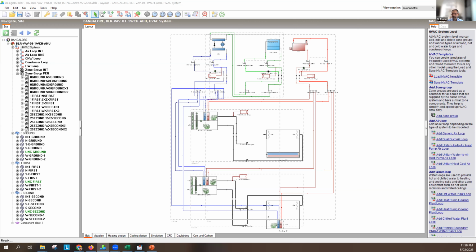So if your refrigerant leaks, your technician will come in, but he cannot refill it straight away. He actually has to decant the rest of the refrigerant and refill it. If he can't find the leak, which he more than likely won't be able to, he'll just refill it and go away. Okay, and over time, this will leak again.